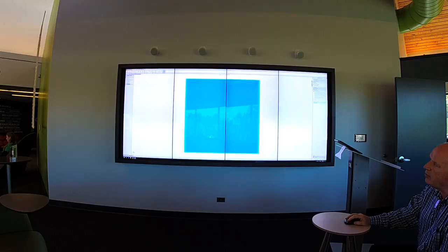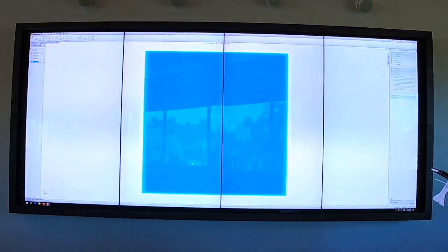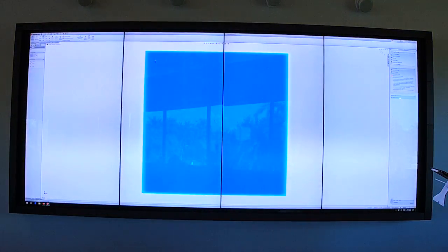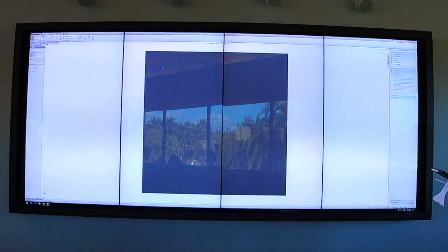So again, we go back to our sketch. Now I'm going to look for a circle, and I'm going to start right up here. Okay, so I've picked one size. Now I want to make that a specific size, so I'm going to smart dimension that again. I'm going to click on that and say I want this to be, let's say, 5 millimeters in size. So that's now 5 millimeters in size. Now I also want it to be a certain place away, so I'm clicking on the edge with the smart dimension and then saying I want you to be 10 millimeters in.